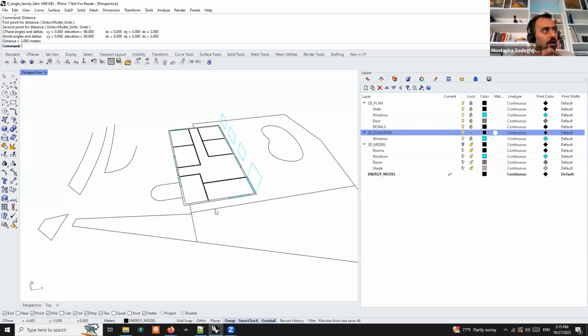So the process is always you build the rooms first, then you add the windows and doors and skylights and everything to them. So for windows and skylights in Pollination, we use aperture because aperture basically covers both of them. So when you hear us saying aperture, basically there's any opening that the light can get through the space.